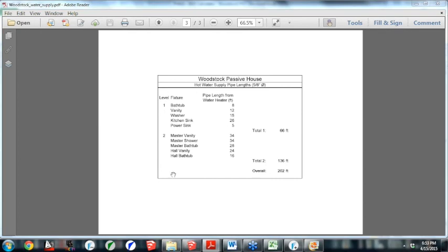You just do a weighted average. That's what I would do. If part of this is off of the main trunk, I would say 4 feet of it is 3/4 inch, 4 feet of it is 1/2 inch. So I'm going to weight it, and that's how you determine the exterior pipe diameter. So yeah, circumference weighted.